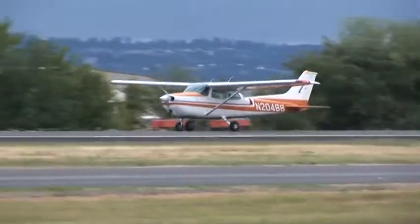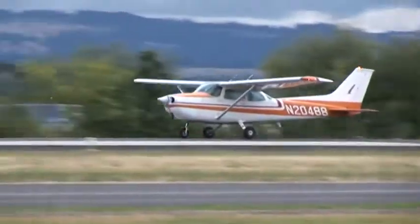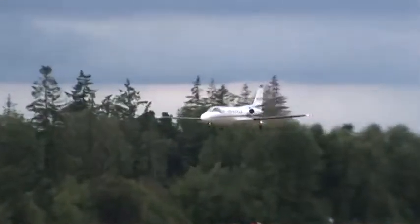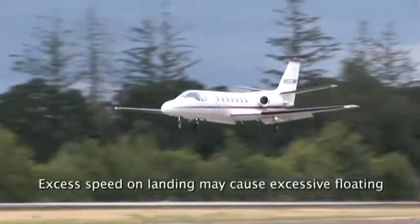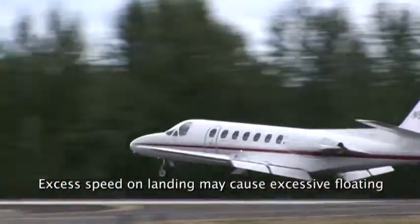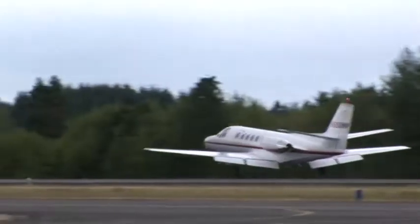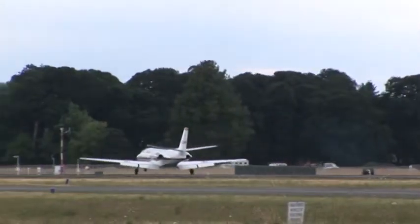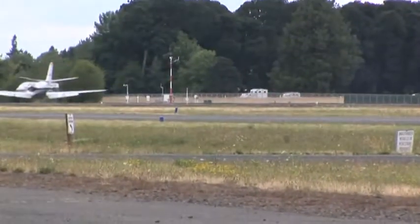This means if you come in for a landing and you're carrying too much speed on final, as you get close to the runway, that is less than one wingspan above the runway's surface, your induced drag decreases. Your wing's performance or lifting capability increases, and the airplane has a tendency to float down past your landing spot. Now, that's not a good thing to have happening when you're trying to land on a short runway.